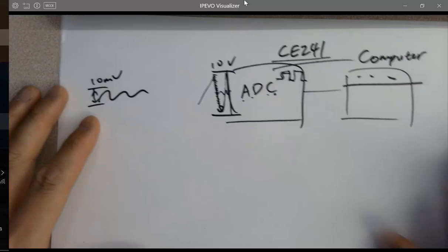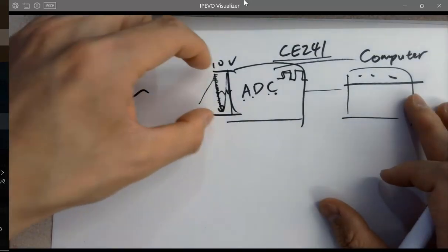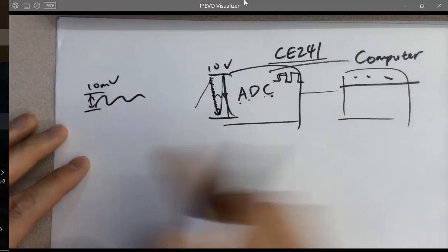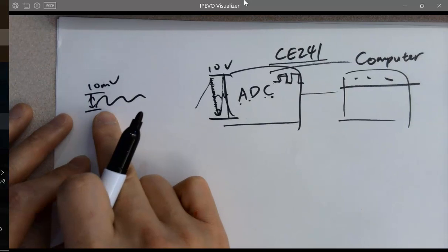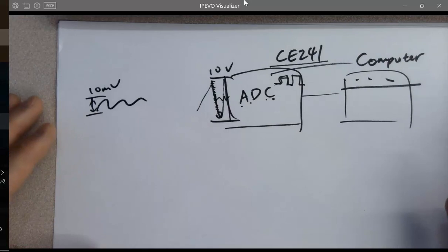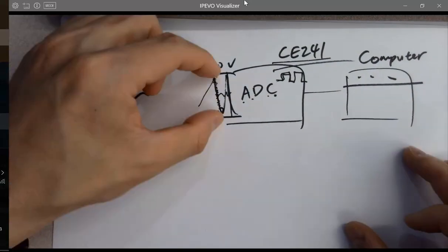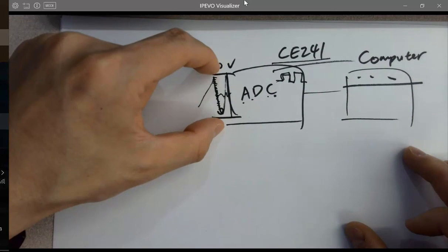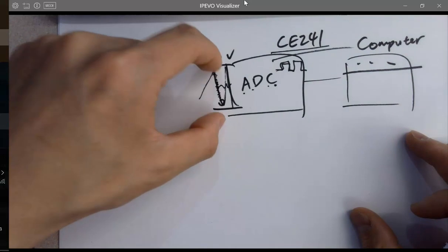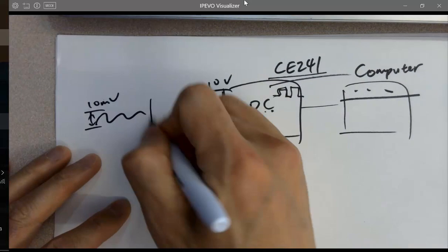So this can still be confusing since you haven't done that before. But just remember that you need to utilize as much as possible of the dynamic range of the ADC. Your signal can be different, it can be tiny, it can be huge. Sometimes you have to shrink it, but that's rare. But sometimes, most of the times, you have to amplify it. In order to do what? In order to use the dynamic range of the ADC, right? Okay. So you have a small signal, but you need a bigger signal swing for the ADC. So you need an amplifier in the middle.